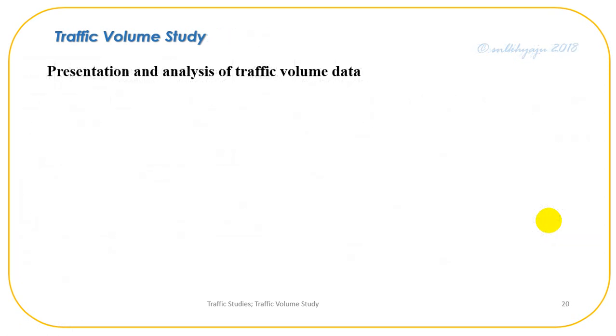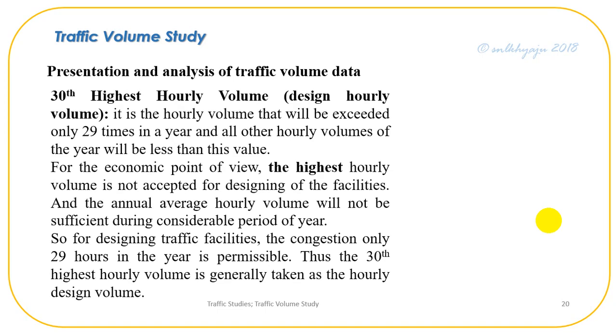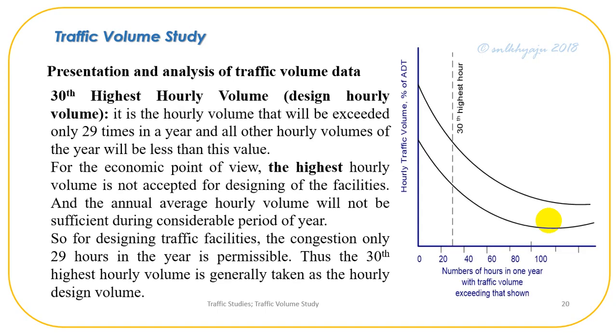Now, presentation and analysis of traffic volume data. First, 30th highest hourly volume, that is design hourly volume. It is the hourly volume that will be exceeded only 29 times in a year, and all other hourly volumes of the year will be less than this value.